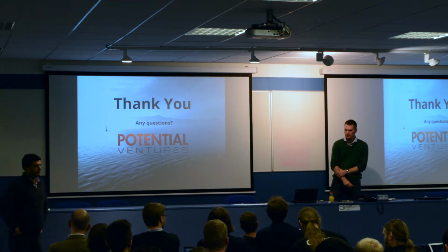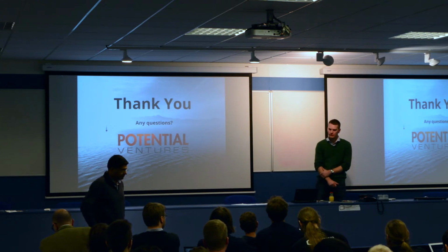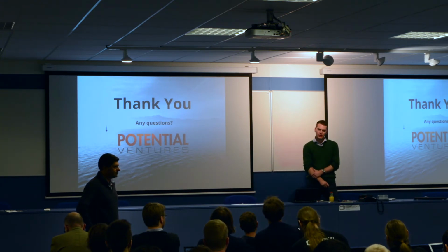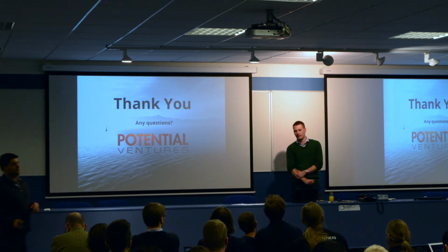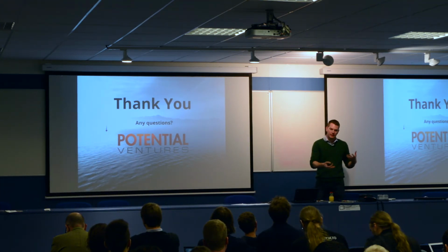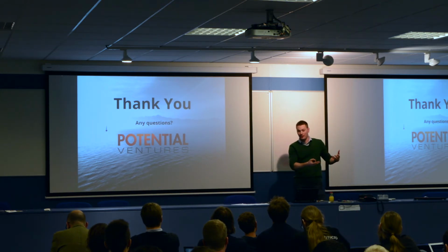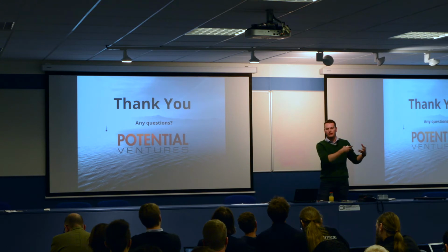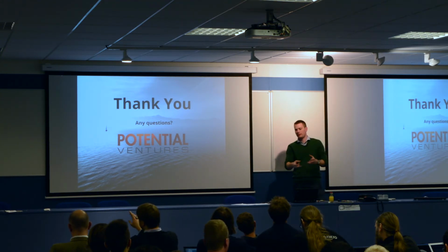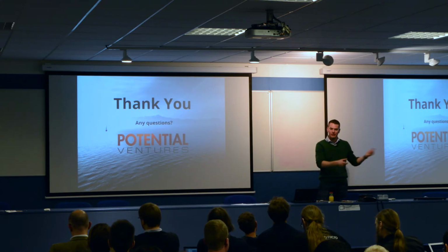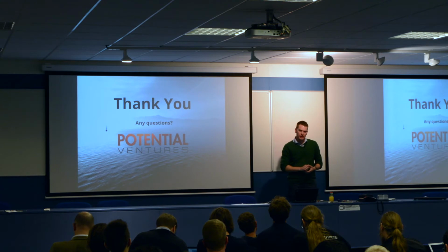Functional coverage. Can you say a few words about the status of that? Is that something you're building into Cocotb, or is it another module you plug in? That's something we're building into Cocotb. Functional coverage is effectively defining a set of counters that increment based on certain conditions, and for complex coverage, you might have some kind of small multiple cycle state tracking device to decide which bin to increment. So it can be quite convenient to do that in Python.